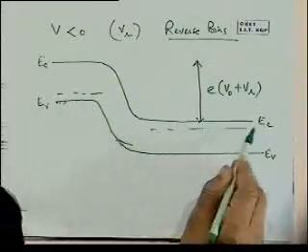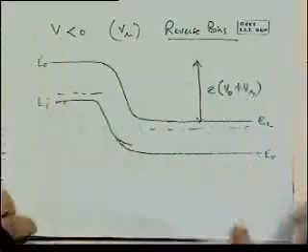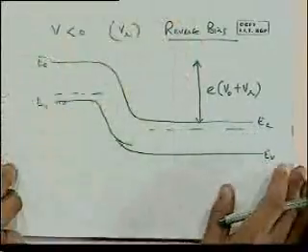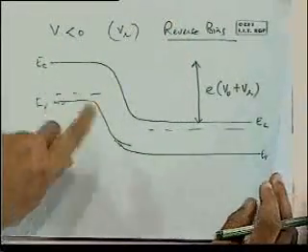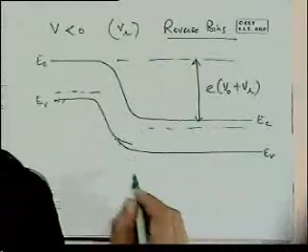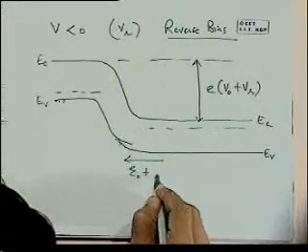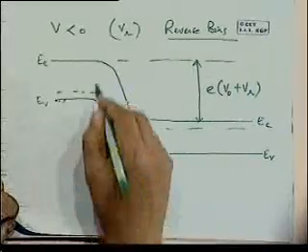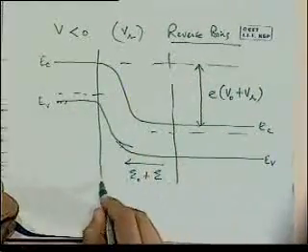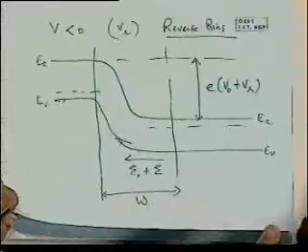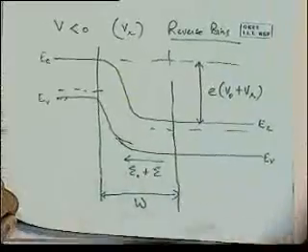Just pretend as if EV is less than EC at this point. We haven't gone to that higher voltage. So in other words, this change hasn't been as much as I've shown it. Because if this is true, then something else is going to happen, which I'll come to in a second. Okay? So this is the situation in reverse bias, probably just a little smaller than what I've shown. The field is now enhanced from the built-in field. The additional applied field is there. In addition now, my depletion layer width has increased significantly from W0 to the term W.